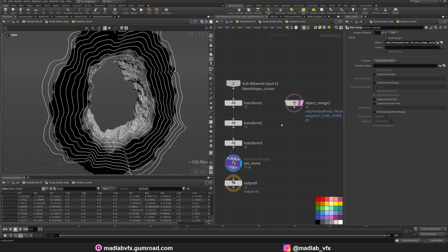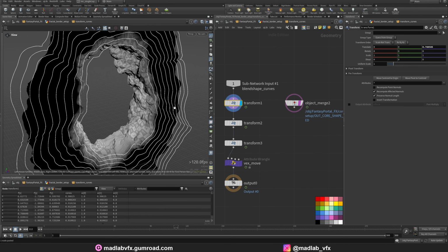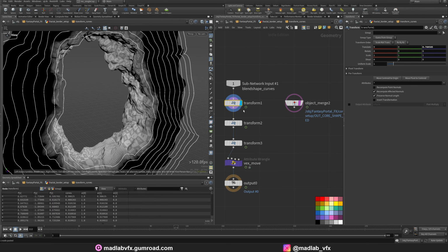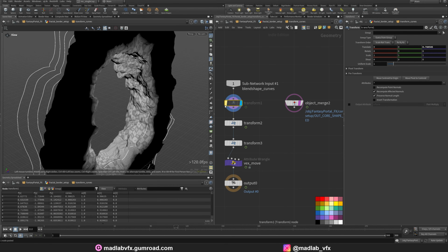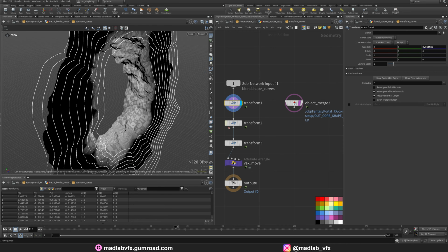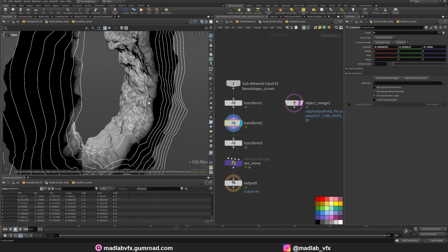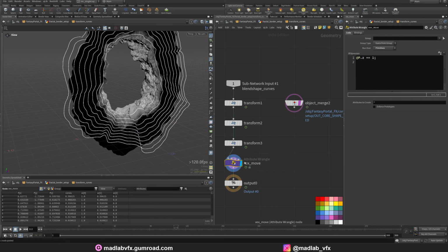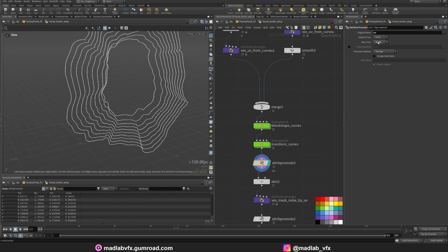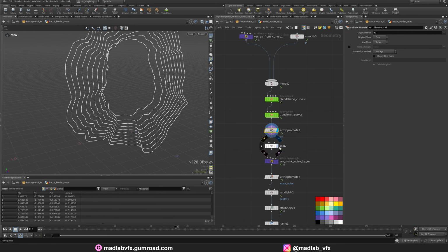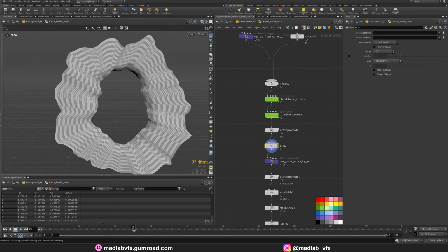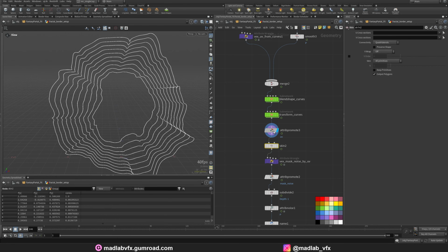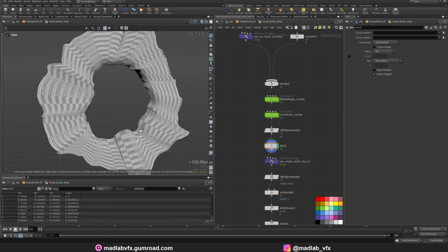Simply I just grab the reference to see where I can transform these points. First, I move this to front. Then I move the first line a little bit back and the second polyline a little bit. Actually, this node we don't need to use, can disable that. I use attribute promote, the UVs to point to vertex. I skin that geometry. You can see here all the lines, just the polylines in skin.